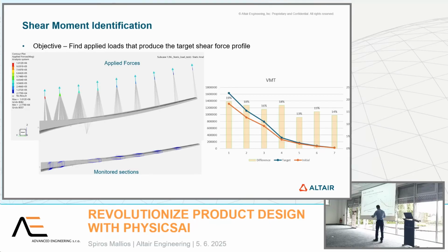So basically, what are the shear moments, torques, and stresses inside the wing structure. And what is the goal here? The goal is to identify what would be the loads applied on the wing, which of course you cannot measure from the actual air, based on the measured data from the strain gauges, from the measurements that you have on the test data.